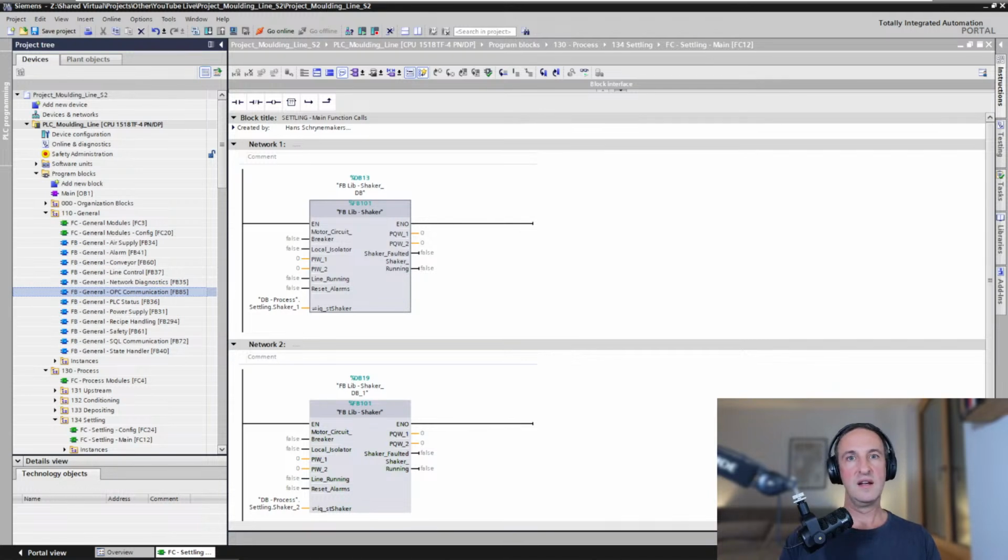That's a cocktail for disaster. You should just have global data connecting to your HMI, tagging up to your HMI. Instance data should purely be in your PLC application and only with your block call. So yes, I do untick those boxes.